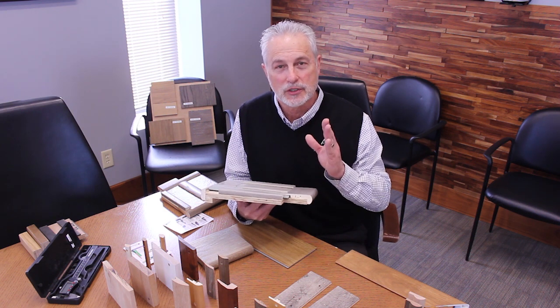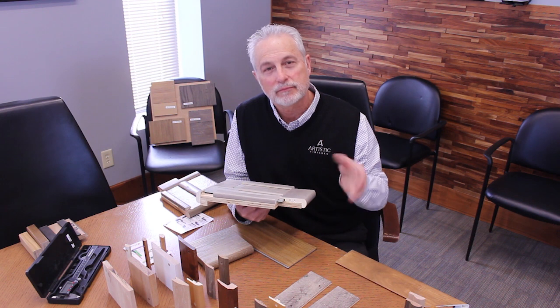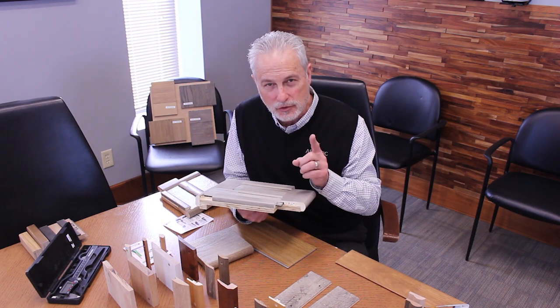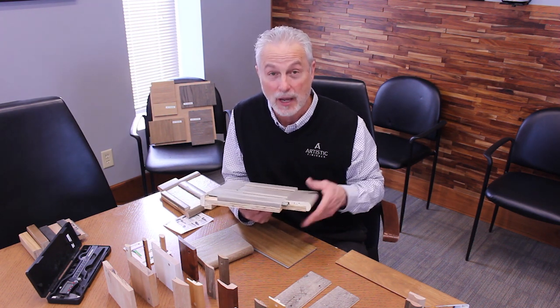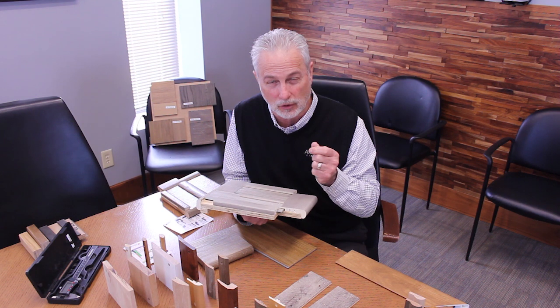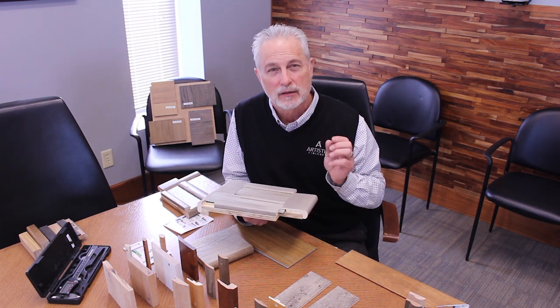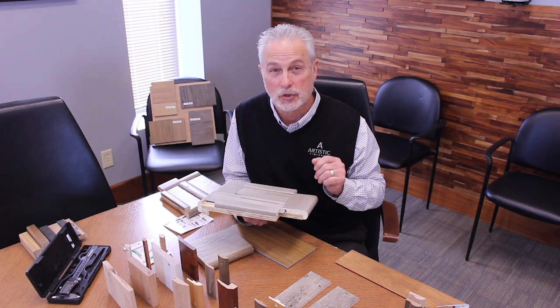So the key difference here and the understanding to get, if the floor is floated, it's going to need an overlapping, unless the manufacturer's recommendation says it's not going to move. You know, some of the new SPCs and the rigid vinyl cores, they're giving wide expansion without a need for movement concern. If that's the case, make sure you know that.